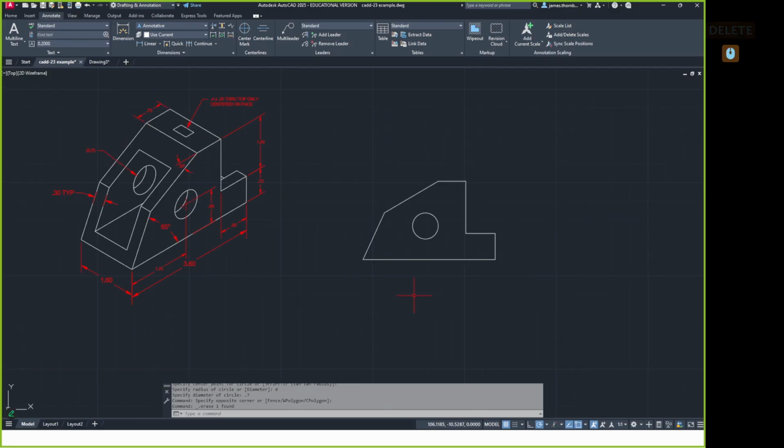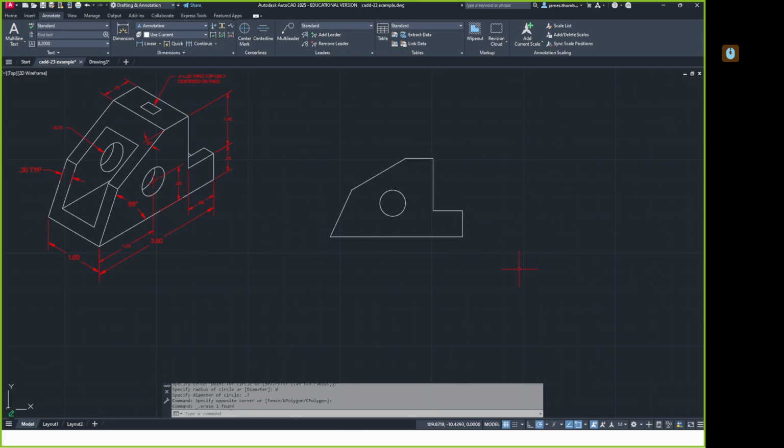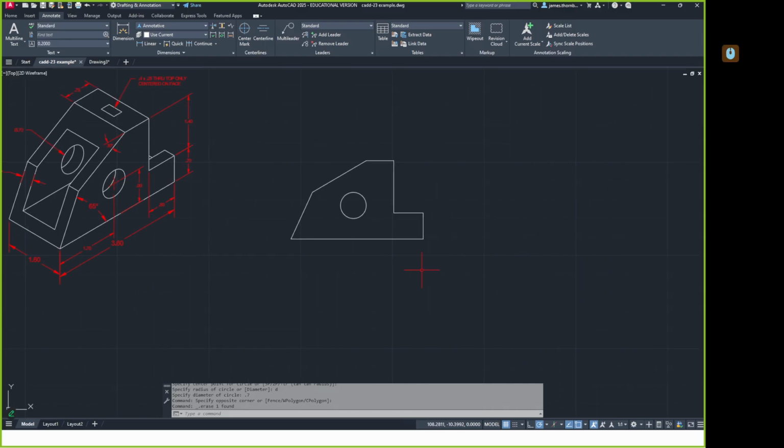A lot of times in AutoCAD, we'll draw things just to find things and just get rid of it. Not too much to get rid of something. Anything else in this view that I can draw? So when we're drawing things, we want to draw things where we can see them. So here it's going to be hidden, so I'd rather draw it in the top view and then project it down than try and draw it in here. So same thing with this cutout here, I can draw it on the side view, right? So this view is done for now.